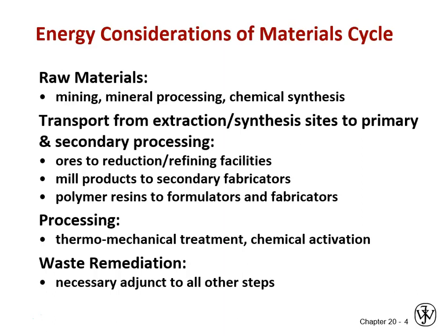Start right with your raw materials. Mining and mineral processing are very energy heavy processes. Most of the raw materials for your chemical synthesis for your polymers start in the petrochemical industry. Sourcing crude oil is extremely energetically expensive as well as just fiscally expensive. So these are all considerations. Primary synthesis is very expensive. In the case of metals, they are generally not present in their reduced zero valence form in the Earth's crust, and therefore energy is required to add electrons to reduce them from ore, and that is very energy intensive, especially for some of our workhorse metals like titanium and aluminum.